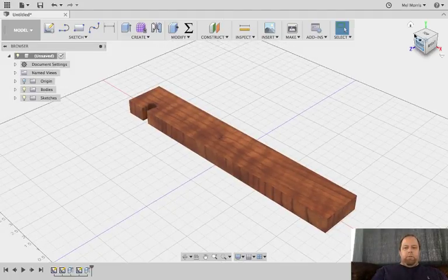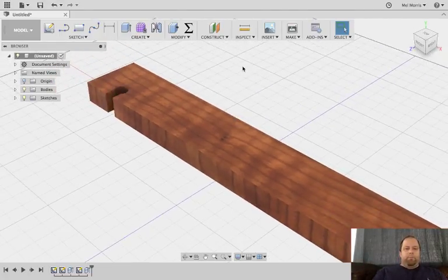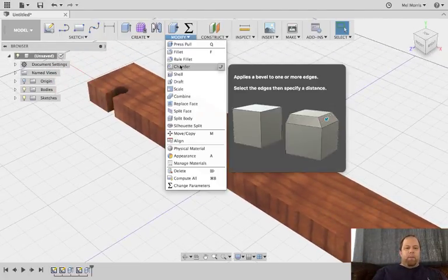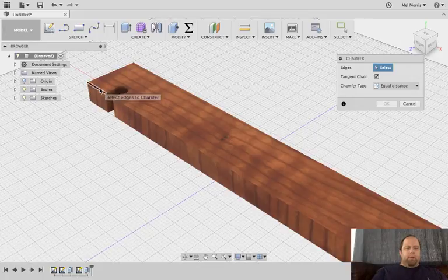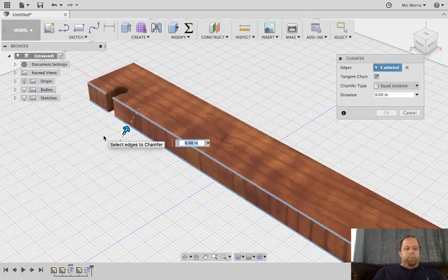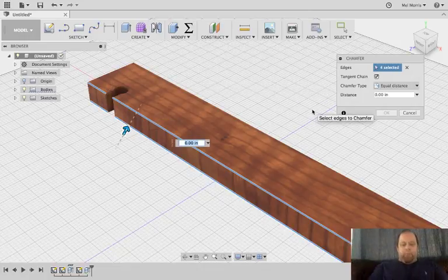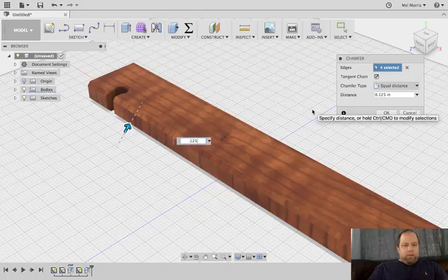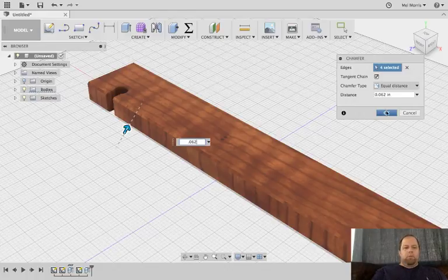Now it's pretty quick from here. We know we want to put a chamfer on this, so let's just do it now. So we can modify chamfer. Now I have to select this one and this line. This line, this line. And 0.125, see what that looks like. A little too much, so 0.0625, which is basically a 16th or so.